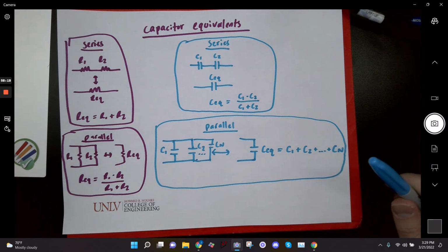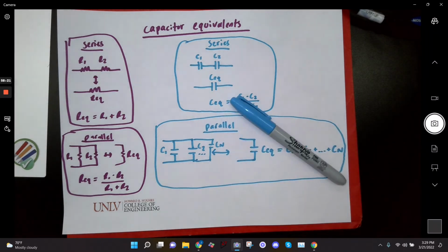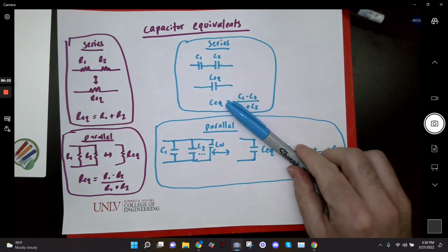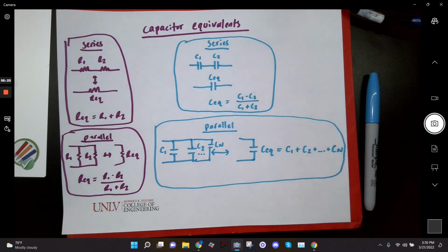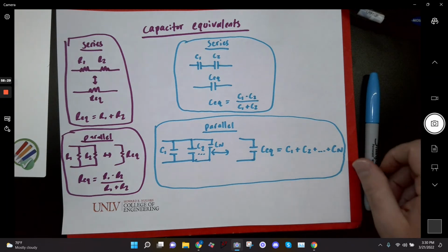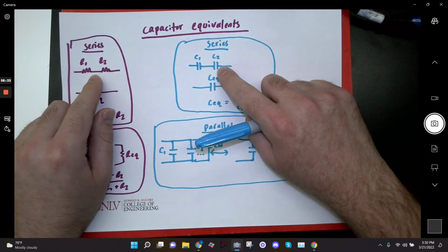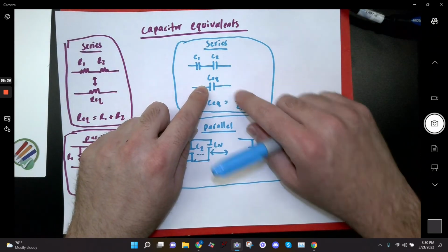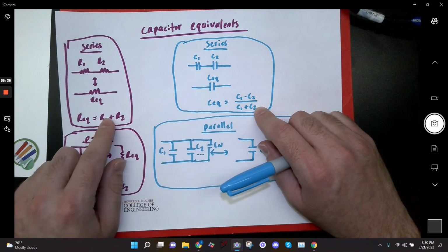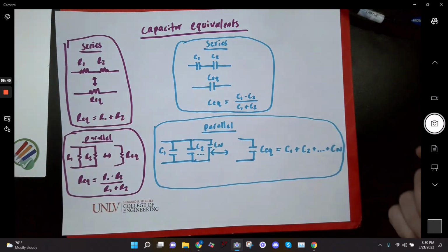All right. So yeah. I don't quite understand when I look at these diagrams. How are the capacitors opposite to resistors? They kind of look the same. They're not opposite. I'm saying that when you have capacitors in series and you want to find the equivalent, you have to do the opposite of what you do for a resistor, and vice versa for parallel.